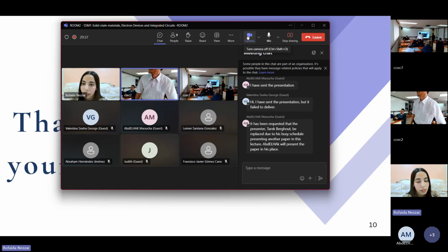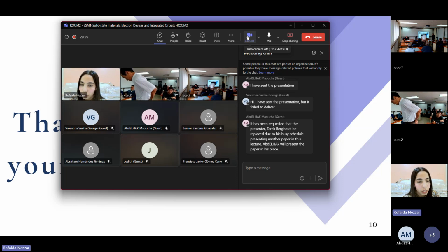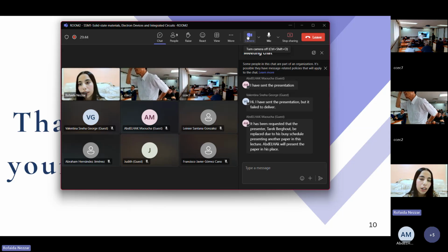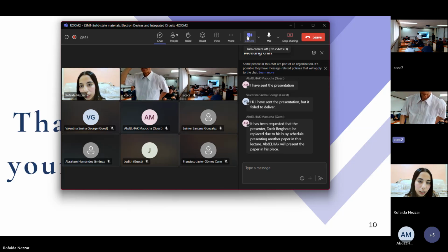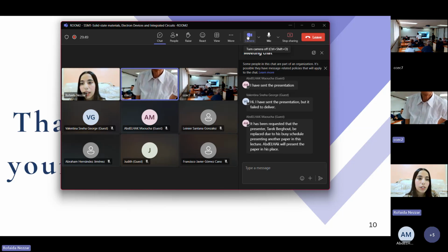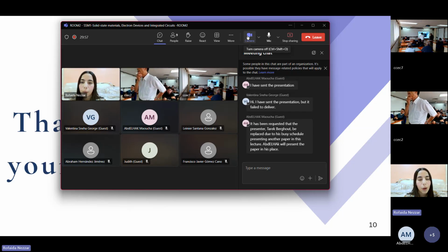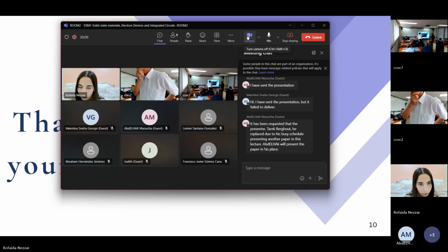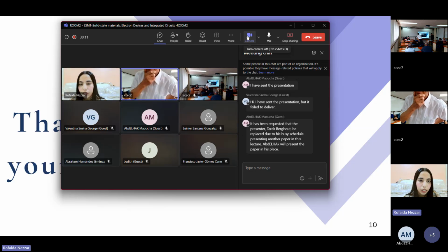So the zinc oxide has a thickness of 100 nanometers. Oh, are you asking for the indium tin oxide thickness? Yes, for example, previous for annealed or not annealed samples. Yeah, both were deposited for the thickness of 108 with silver. So zinc oxide has the thickness of 100 nanometers, and the silver has the thickness of 8 nanometers. Okay. So combined, it's 108.